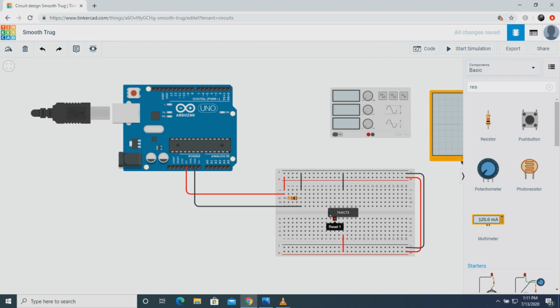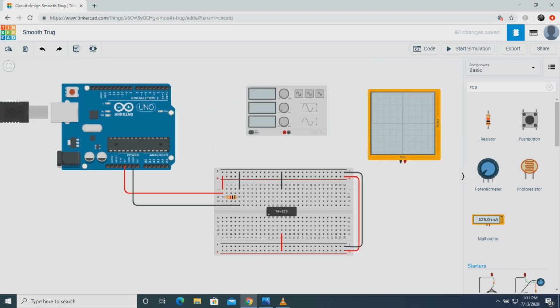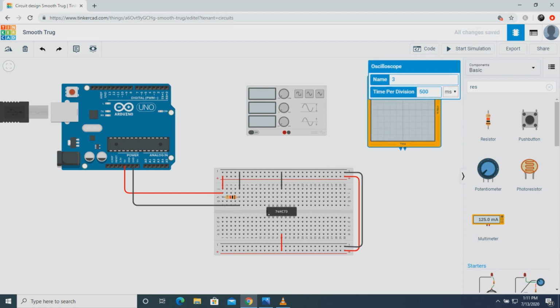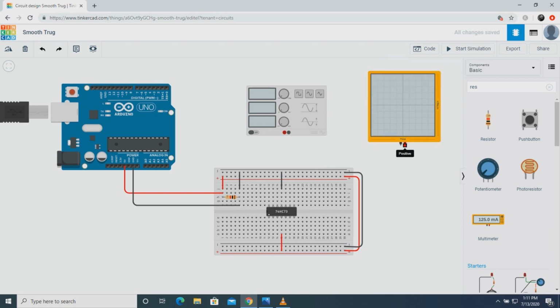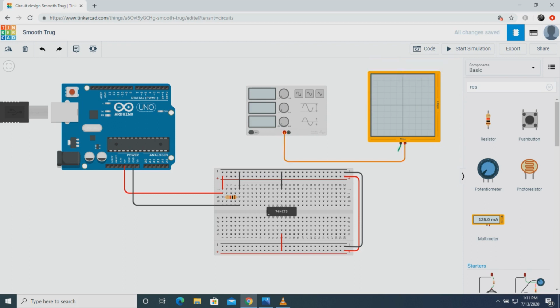Now for the clock, as I have prepared the clock, let me do this. So for the oscilloscope feeding, let me use a different color for the oscilloscope probes, as this is the oscilloscope probe. Let us use the orange. And this is supposed to be ground, and we need to make a common ground connection. So you use it here, you make it black. Now from here to another node.